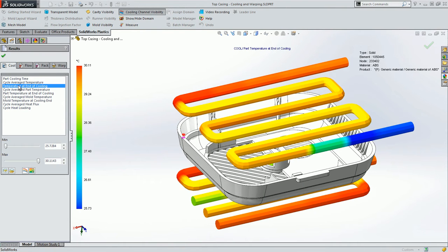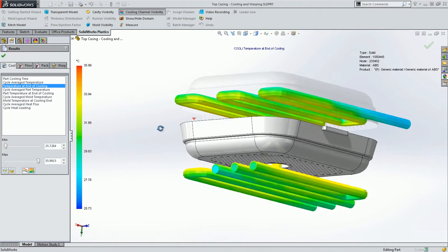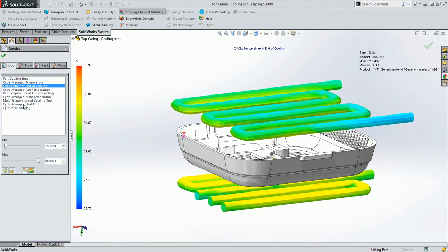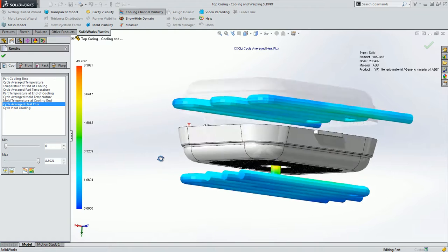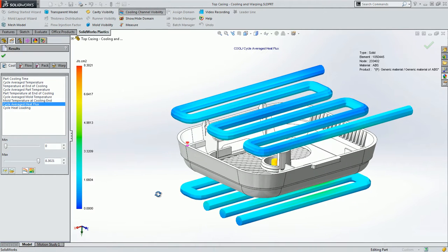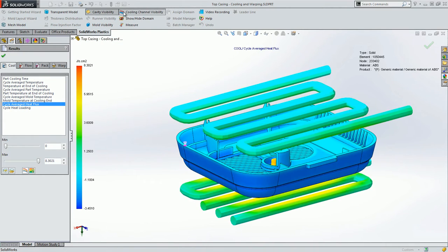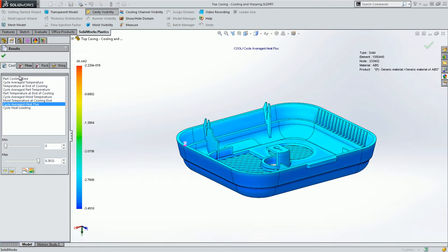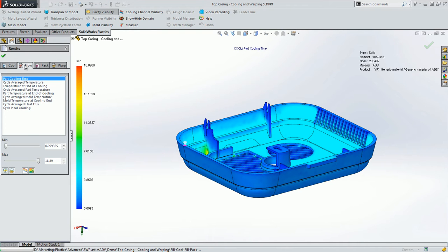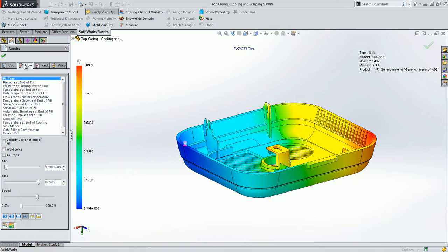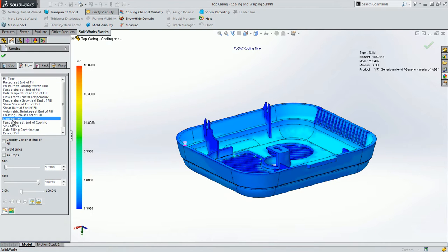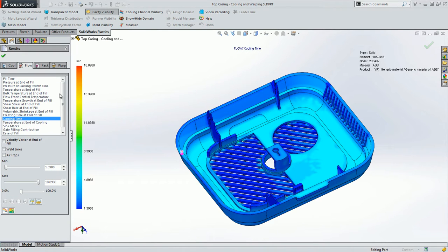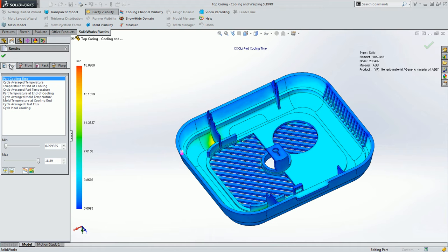By highlighting just the coolant channels, you can also identify where most of the heat transfer is occurring by showing the heat flux. Another valuable aspect is to understand the differences between the analysis without accurate mold and cooling. By looking at the predicted flow results, we can review the estimated values based on a uniform mold temperature during cooling. The flow predicted cooling time is very similar to the accurate analysis at just under 19 seconds.